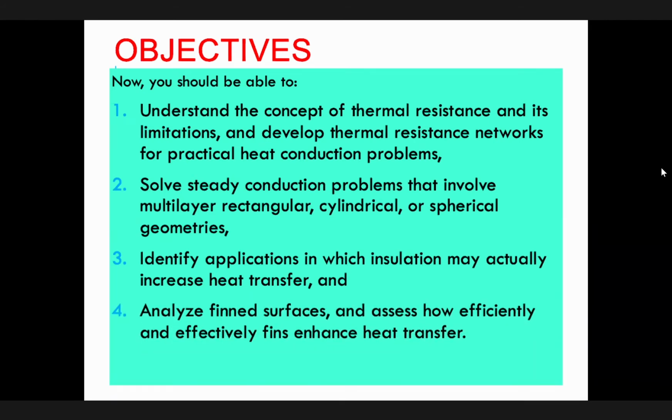Now the last lecture and this lecture we devoted to fins, okay? Fin surfaces, and assessing how efficiently and effectively we can use fins. As I mentioned, sometimes we would like to reduce the energy transfer by conduction as much as possible, and the only way to reduce it is by adding insulation, okay? But in some applications, we would like to encourage heat loss. In order to increase heat loss, we use fins. Again, the reason is that at the end, you have to lose the heat to the outside environment, and that's by convection. And when it's by convection, there's a temperature difference that you cannot do anything about. The only two variables remaining are H and A.